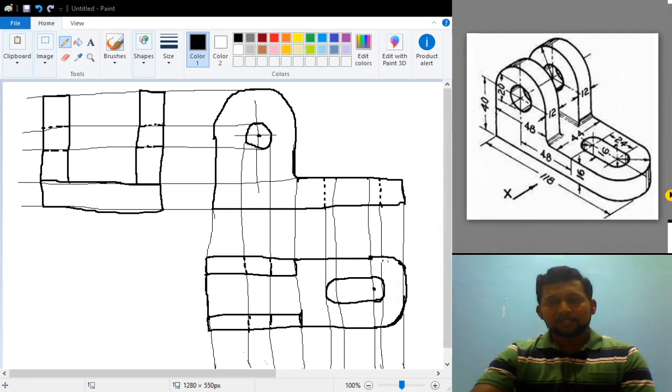Okay, so when you are seeing from the side view, you should be able to see 16 mm. So in this 16 height block, you try to draw a vertical reference line, a very small vertical reference line. Okay, so once you draw that vertical line, to the left hand side you have to take 8 mm, and to the right hand side you have to take another 8 mm. Why? Because this block distance, this whole distance, is how much, 16. Okay, we are not worried about this particular distance, that particular distance becomes 0 in the side view. We are worried about this breadth distance. This breadth distance is 16 mm for that hole.